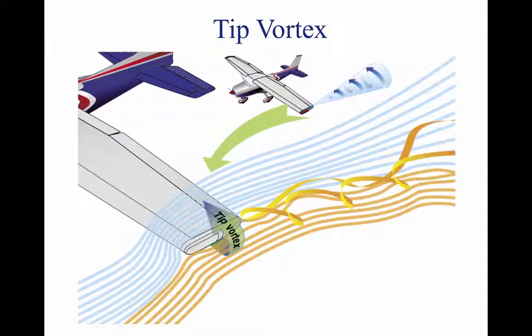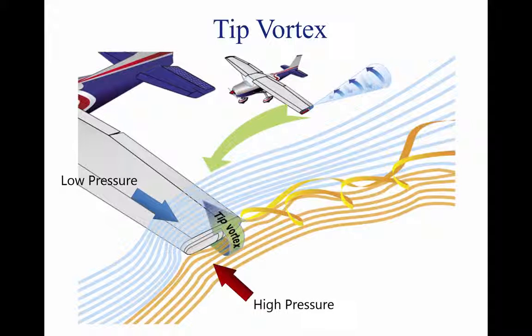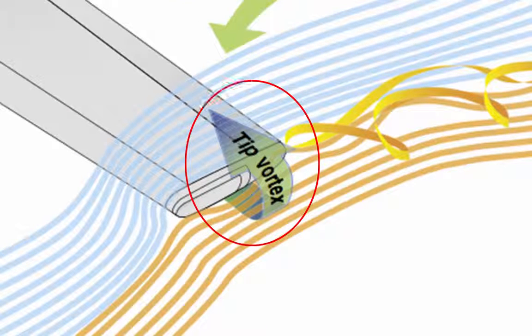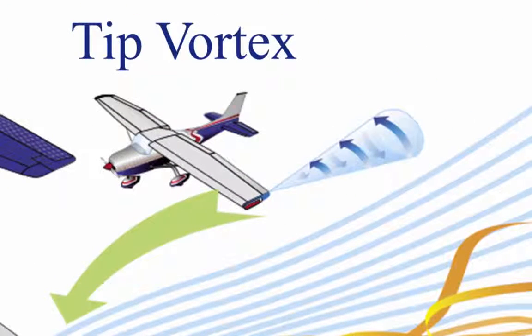When we talked about lift, we were talking about the lift caused by air flowing over the center part of the wing. If we look at the tip of the wing, there is a phenomenon that occurs known as tip vortices. When reaching the edge of the wing, there is still a low-pressure zone above the surface of the wing and a high pressure below. These pressure zones naturally want to even out, so the high-pressure air tends to flow towards the low-pressure air. The high-pressure area on the bottom of an airfoil pushes around the tip to the low-pressure area on the top. This action creates a rotating flow called a tip vortex.